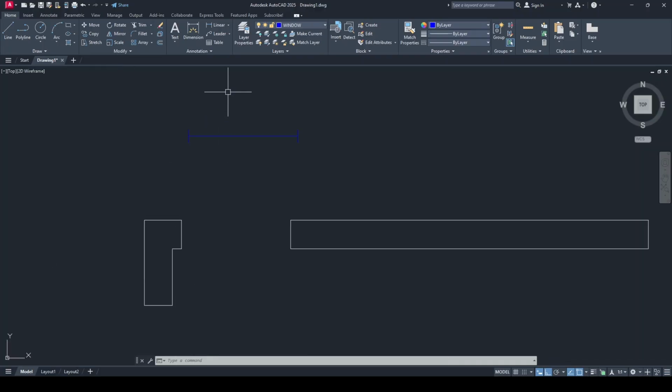Zoom in a little, click once on the window. You can see all these grips. The only one we are concerned with is this one. You can click it once. There are some predefined distances. If you click on this, there is 600. There is up to 1500. Our window opening is 900. Make sure you're on the 900, which is this one. Press the escape key.